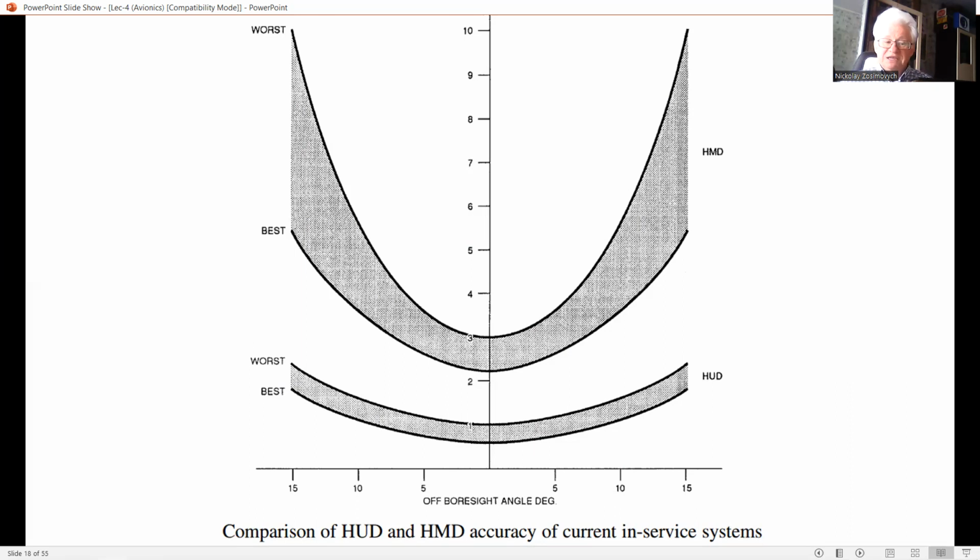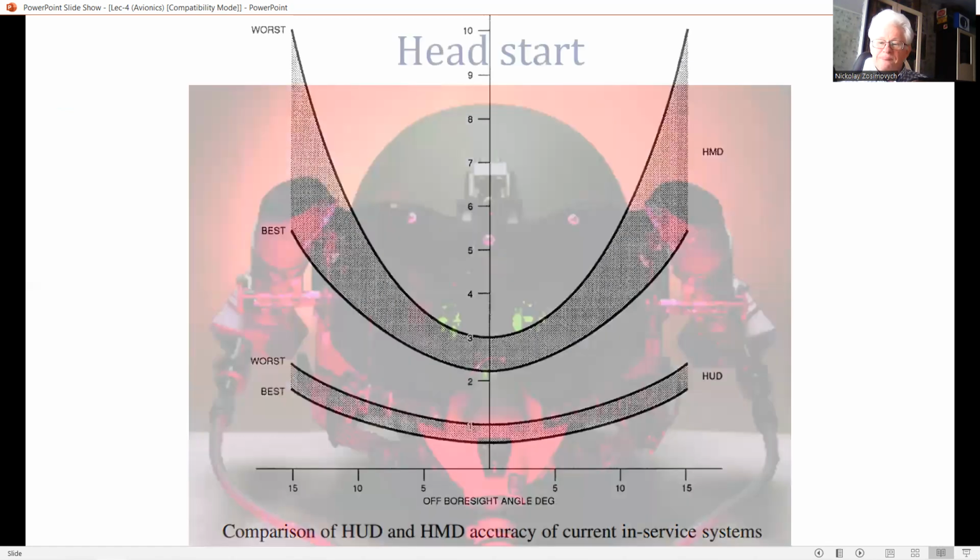In future conflicts, it may therefore be necessary to fly with a suitable opaque visor installed on the helmet to protect the pilot's eyes from optical weapons when operating in areas where such a threat exists. The pilot would then fly the aircraft by means of a head-steered indirect viewing system with overlaid flight and weapon aiming symbology.